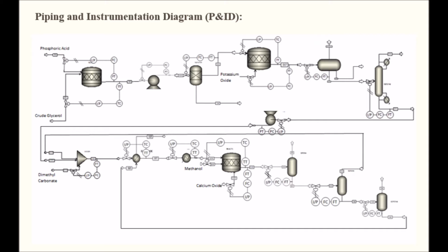At the same outlet stream, there is another temperature control system attached. When a differential value of temperature is detected by the transmitter, then the feed flow rate of another feed stream will be controlled in order to adjust the temperature. Therefore, the converter and control valve are attached to the feed stream.